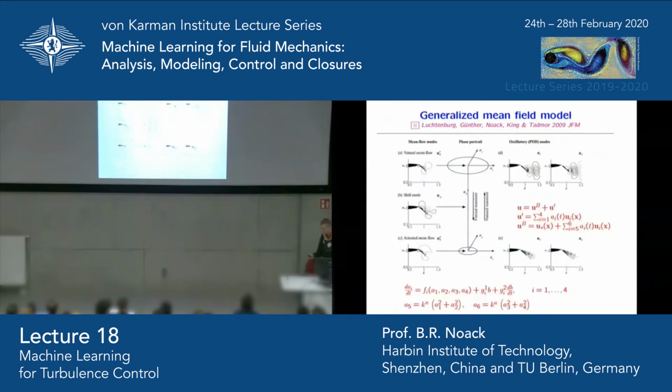this. We have now two states. There is one limit cycle corresponding to the natural setting, which we can resolve with the POD modes without actuation. There is another limit cycle with the actuated flow. So these are two other POD modes which we use. The total fluctuation now has four POD modes, which you see here. And the base flow somehow has to respond to the strengths here and the strengths here. As I will explain in a second, each of these Reynolds stresses from this fluctuation and this fluctuation changes the base flow. So we get two additional shift modes, or two additional modes describing the base flow variation.